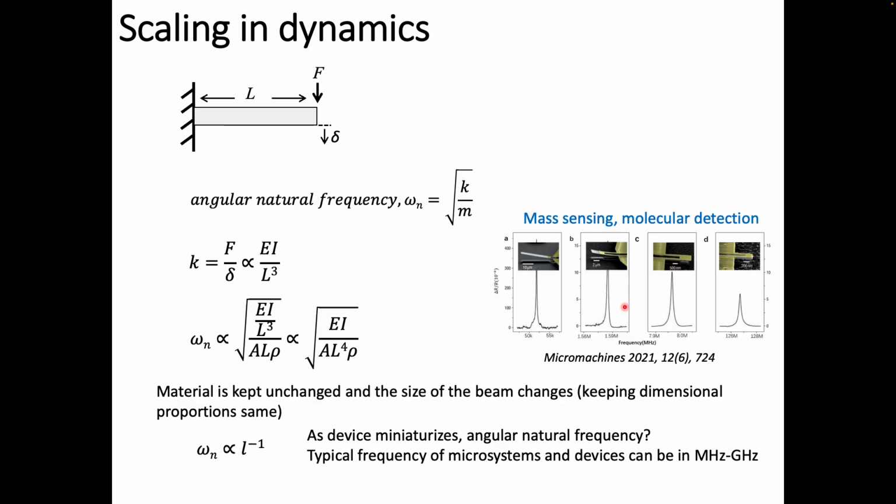At this natural frequency, the motion is so crazy, right? But if you go a little bit away, what happens? Nothing, no response. Unlike the washing machine, in this case we are using the motion near the natural frequency. That's essentially how we detect the mass change.